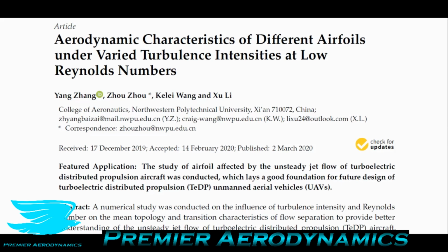So you need to make sure that you get the same turbulence intensity, and trying to change the turbulence intensity in a wind tunnel is quite difficult. You can take out mesh screens, but then you have to put a hot wire or whatever in there and measure the turbulence intensity, and you don't get to change it to whatever you want. You get discrete levels. Like if you have 3 screens in there, you might get a certain turbulence intensity. When you put 4 screens in, you get a different one. It's not a continuous scale. You have discrete levels that you can put it at.